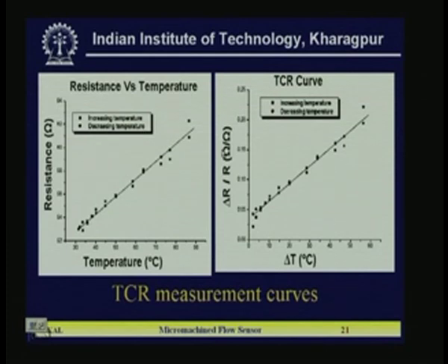With temperature increase, resistance value will increase, and if you reduce it, it will follow the same path. You can see the square and the dot are almost close. We have taken an average curve; there is some small variation because you are taking spot measurements, and stabilization during that spot is another problem. The power supply has to be stable because you are sending a constant current source, so minor fluctuation may be there.